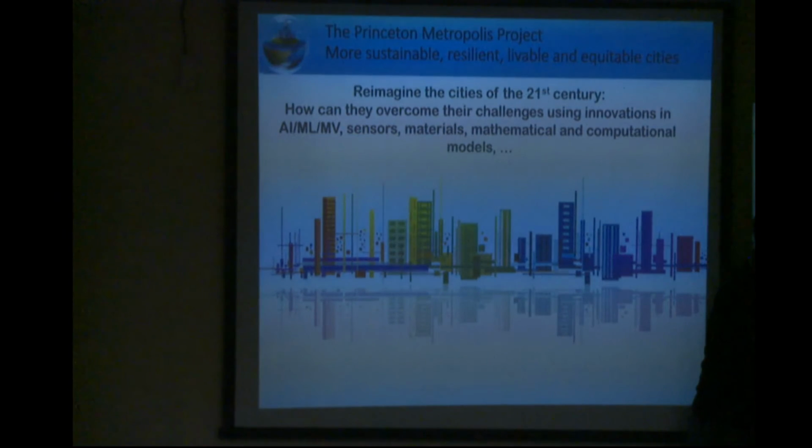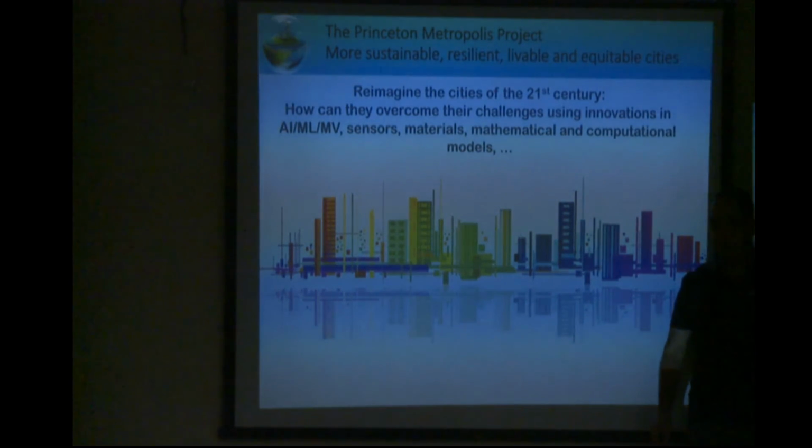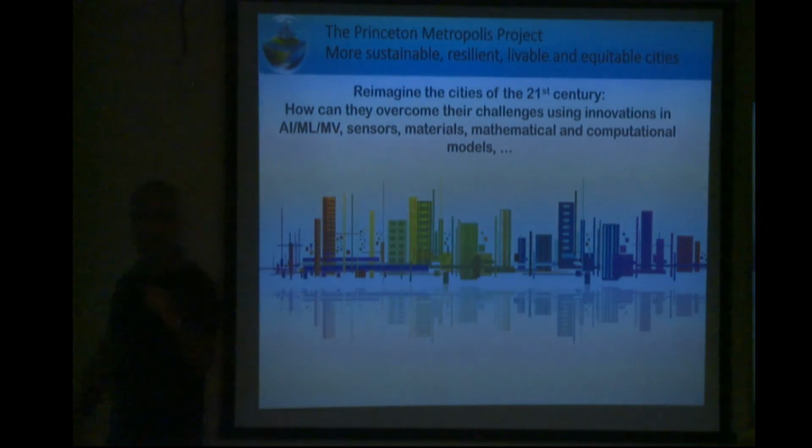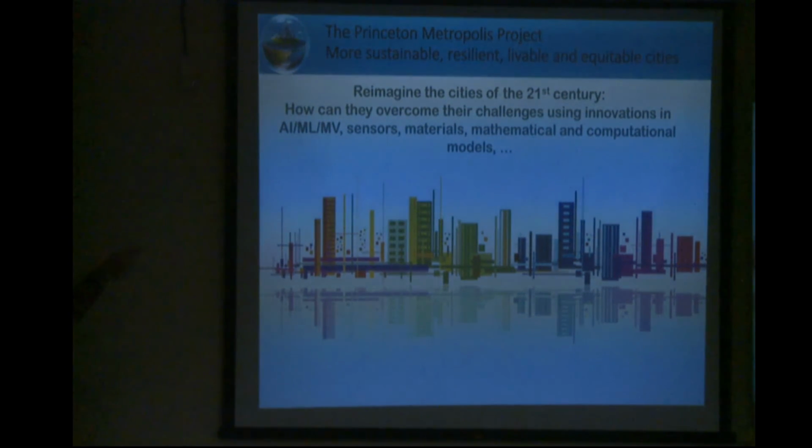For heat, you measure the temperature in the flow and the temperature of the surface, and you model the heat flux here using a wall model. The wall model for heat and momentum is to compensate for these boundary issues. This represents the pressure drag, and for the viscous drag and the viscous heat exchange, you need this wall model. This is much more tricky, as it is trying to resolve the viscous sublayer. This is why wall modeling is more important for heat, because that's the main source of heat, and why it's more challenging.